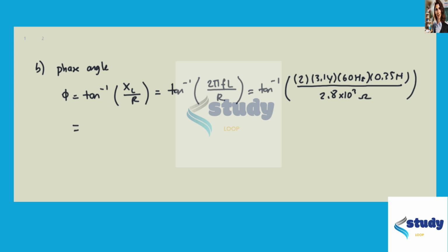From here, the calculation is going to show us that the phase angle between the voltage and the current is 2.7 degrees. So in part C, the power dissipated. So the power dissipated, as you know, is proportional to I, the square of the current, times the resistance. And in this case, we have the RMS current, right? So then what we calculated, our answer to part A was